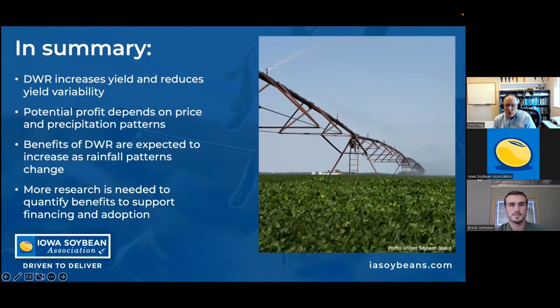Some of the work we did looking at potential sites in Iowa and Indiana suggested about 2 to 4% of the area that you're irrigating would be the surface area that you need for that reservoir to try and get that 4 to 6 inches of storage.